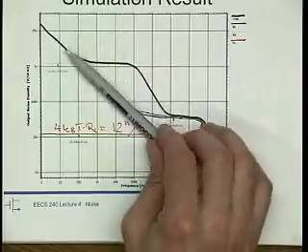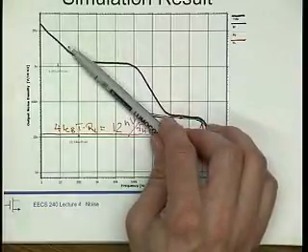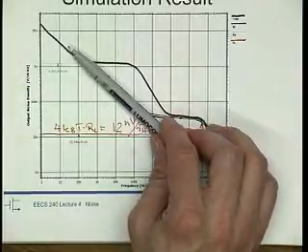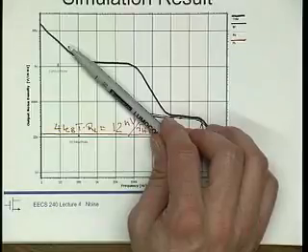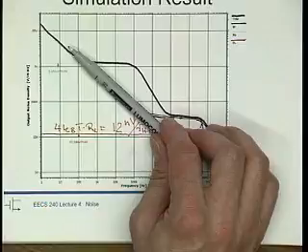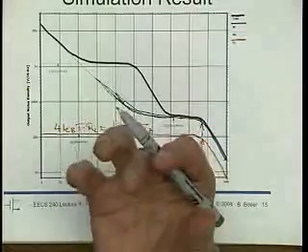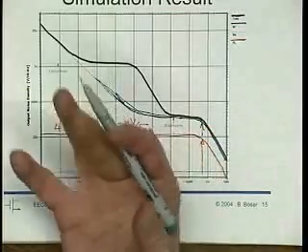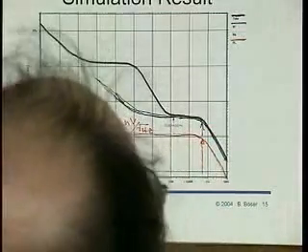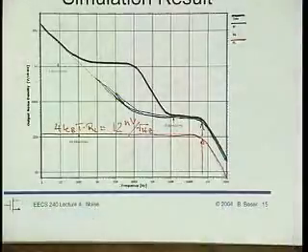Here, this is flicker noise, and flicker noise goes with 1 over S. Power goes with 1 over S. So voltage actually goes with 1 over square root of S. So we get 10 dB per decade attenuation or slope. Right? Funny, but it helps. It's kind of a godsend, because we can see right away: a strange slope has got to be flicker noise, right?